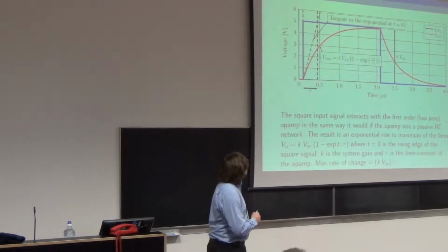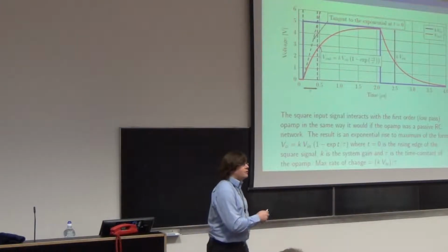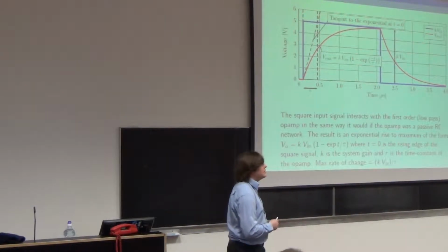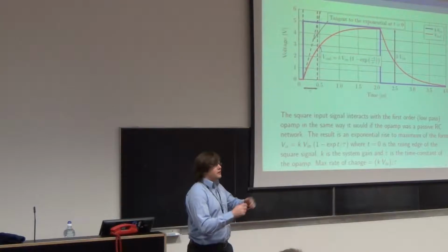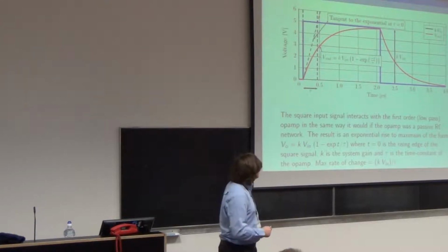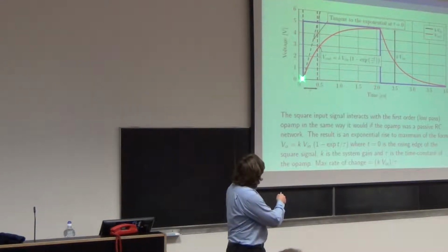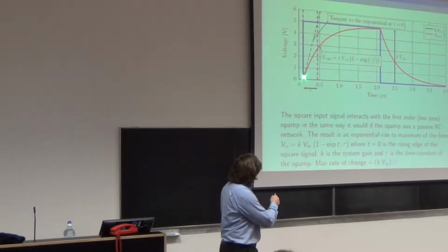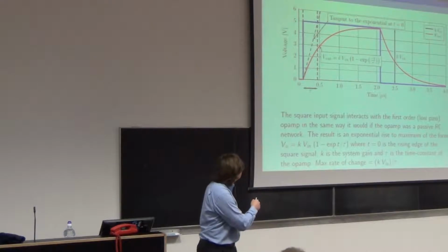So, we will look at the rate of change of voltage across the compensation capacitor, pretty much. And we will neglect the fact that the op-amp is full of transistors for now. We can only manage this dV/dt here, which is the dV/dt at t equals 0 for the square wave.